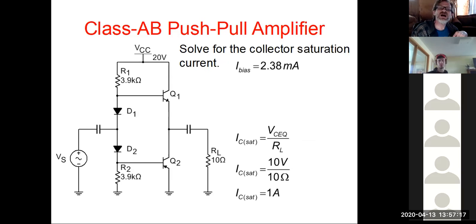Notice on the right-hand side, there are no resistors to develop any voltages for either Q1 or Q2. So these are going to be totally current driven. If you put a probe on there, you're not going to see any voltages per se. You would have to break the line, and then you can see what our operating current is going to be.